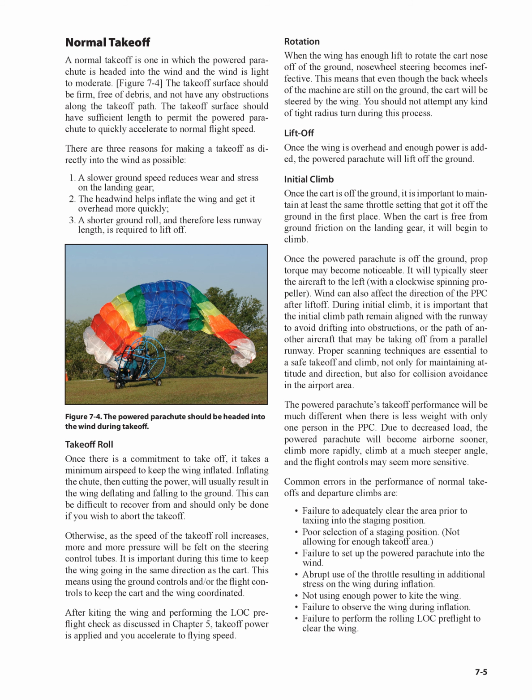1. A slower ground speed reduces wear and stress on the landing gear. 2. The headwind helps inflate the wing and get it overhead more quickly. 3. A shorter ground roll, and therefore less runway length, is required to lift off.